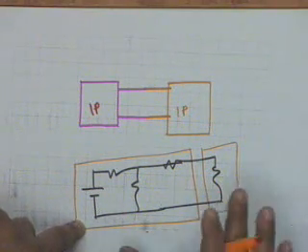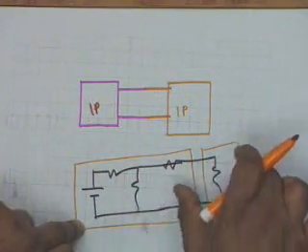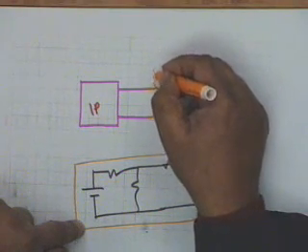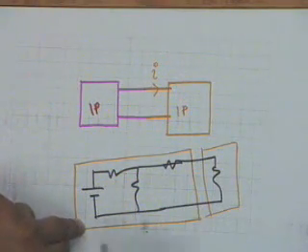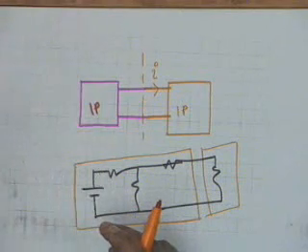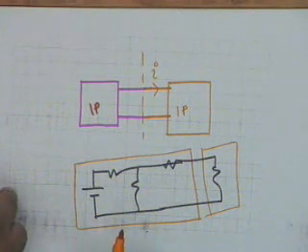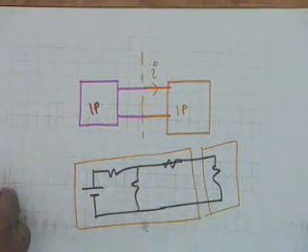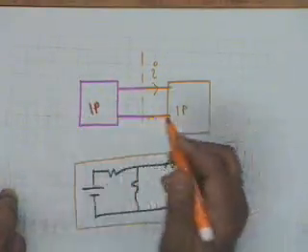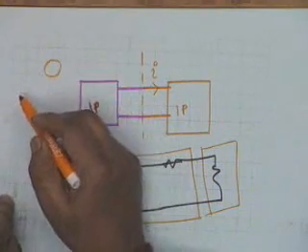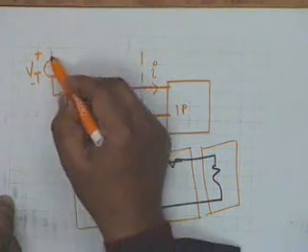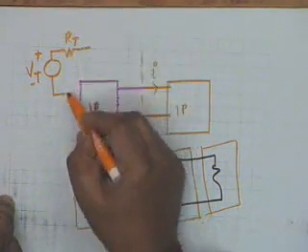All right. Now whatever be the composition of the 2 one ports, it turns out that in so far as this current, let us say I, is concerned, the one port to the left can be replaced by an equivalent circuit, and this circuit consists of a voltage generator Vt in series with a resistance Rt.